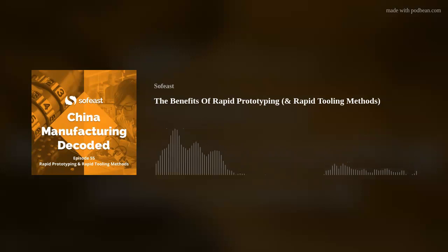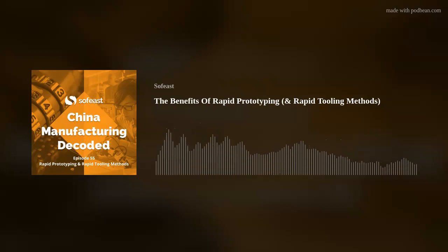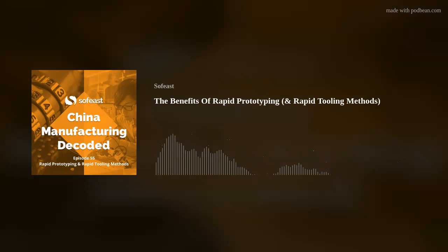And if you need to adjust it, then you make a new mold, make some new parts, and test them again. The turnaround time is days, not weeks or months. That's the big advantage of using silicone rubber. So it's effectively like a temporary mold that you can use to get a few prototypes. Yeah, exactly.